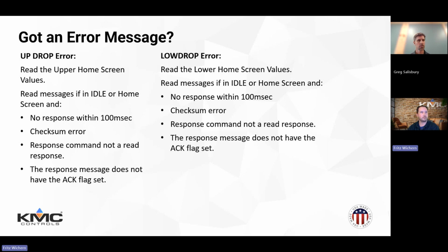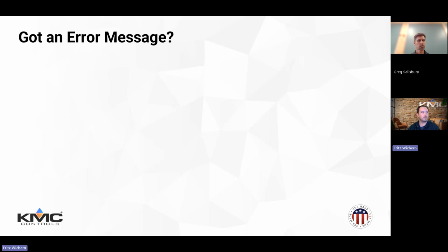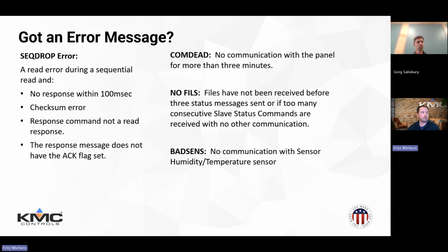And then finally, we've got a couple sequence drop errors, and then COM dead, no communication with the panel, which I actually ran into this morning. I set one of these up last week before I went out of town, a distribution board, and had some NetSensors set up, and had plugged it all in, and then went out of town and came back for the training this morning and realized I had COM dead flashing on my sensor ports 2, 3, and 4.